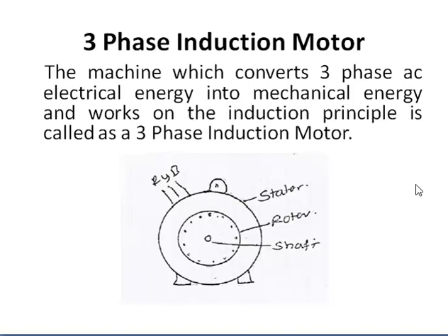The three-phase induction motors are the most widely used electrical motors in the industry. They run at essentially a very constant speed, whether you put it on a load or no. So almost it runs with a constant speed. Whenever we need a change in the speed, this is not a good choice. Whenever we need a change in the speed, mostly DC motors are preferred, but most of the industry requires constant speed, so we can see a heavy usage of the induction motors.